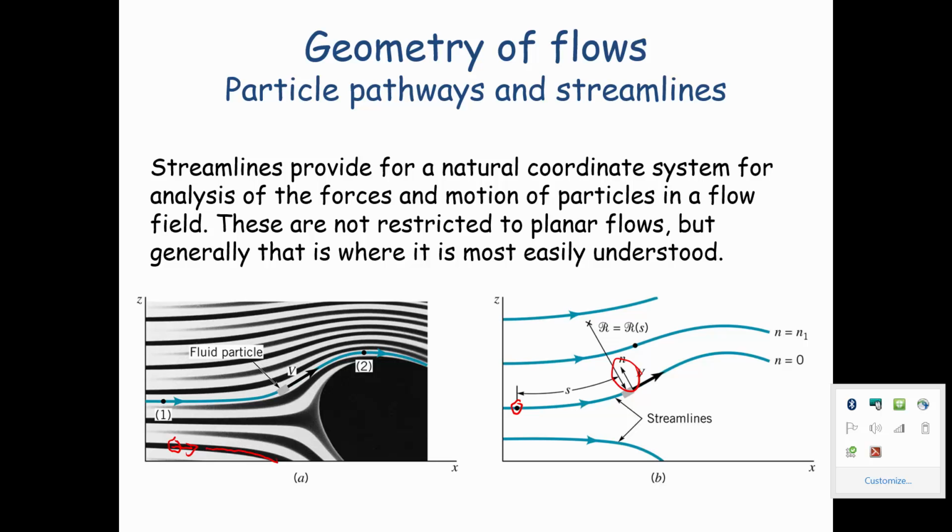And in this figure, the amount of bending is very much variable as you pass along the streamline. On the left hand side, the streamline is fairly straight. If we were to draw a radius of curvature, basically if the line is straight, the radius of curvature would be infinite. Capital R would be equal to infinity.